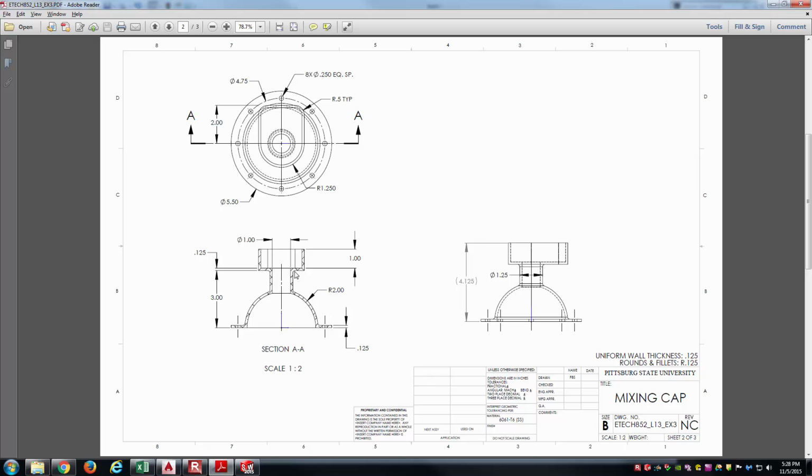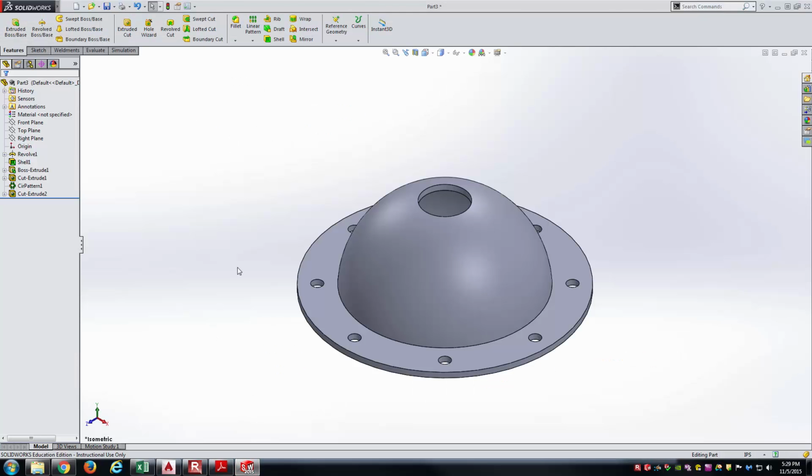And one thing you can see is the next feature that really starts is right here at this 3 inches above the very bottom datum, if you will, of the part. And so one thing I could do is make a reference plane there at 3 inches above that top plane, and we can create this column piece below it, and then we can also create all the geometry above it, which I think is a reasonable idea. And so let's go ahead and create that reference geometry.